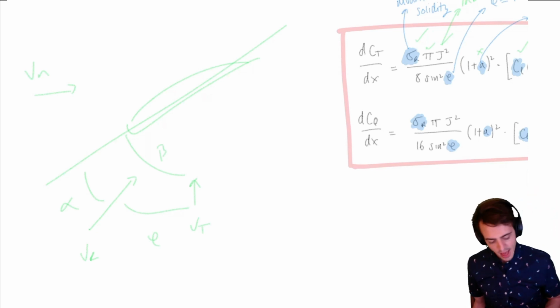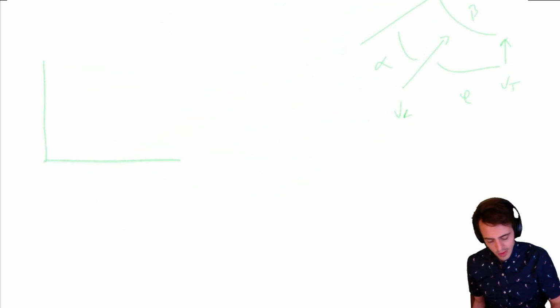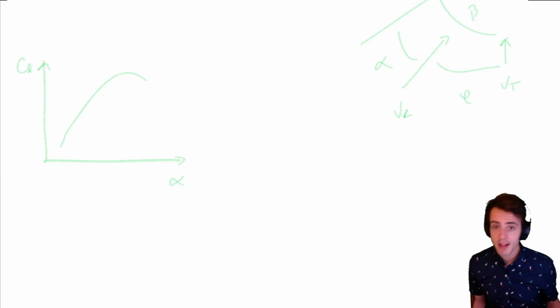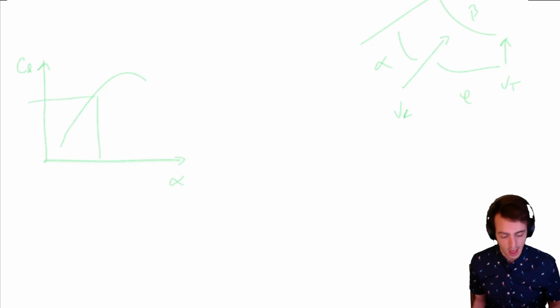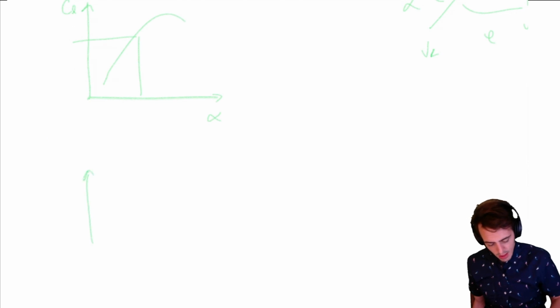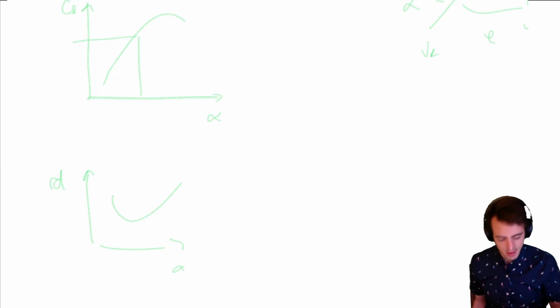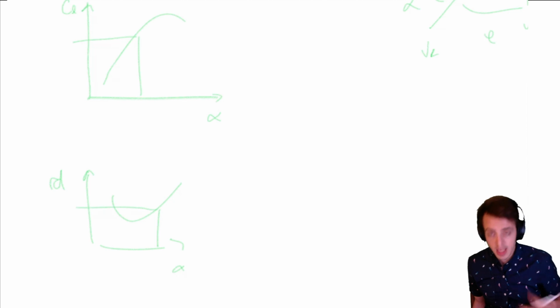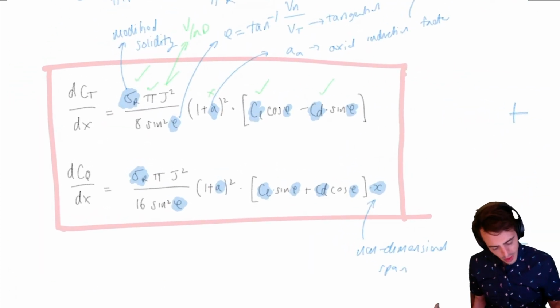And if we can determine the angle of attack, we're working under the assumption for the moment that somewhere we've got some sort of lookup table for our propeller. So we've got CL versus alpha. We've got something that maybe looks like that. And we can say, well, for this angle of attack, we've got some value of CL. And probably we've got something that looks like CD versus alpha. So we've probably got some other table. We can look up for the same value, we can get our CD out. So again, I'm going to put a tick next to those because we know them.